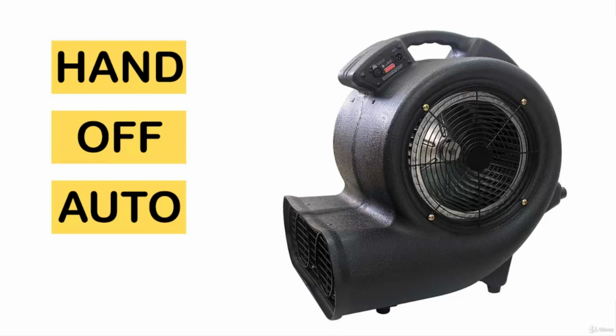For instance, when I push hand and let go, maybe the blower should start running and continue to run until I either turn it off or put it into automatic control. Another possibility is the hand button works like a jog. When I hold the hand button down, the blower runs, but when I let go, it stops running. Then the last consideration is, when the blower's running in automatic mode, can I put it into hand?